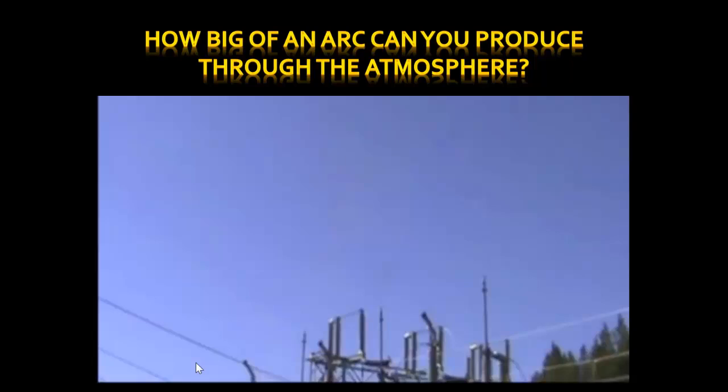Cool air rushes in underneath to take its place, and then the arc just continues to rise, and that increases the distance that the electrons have to flow through the air, and pretty soon the distance is too great for the voltage. In this case it was 138,000 volts. Then the arc is interrupted.